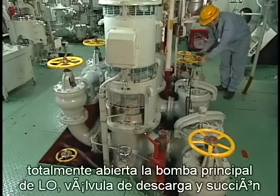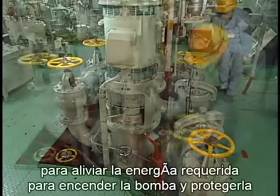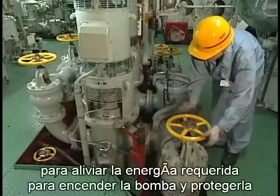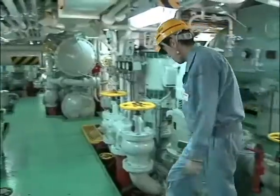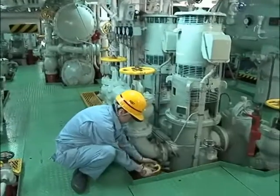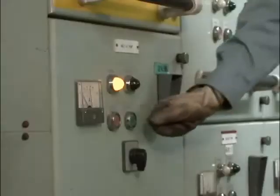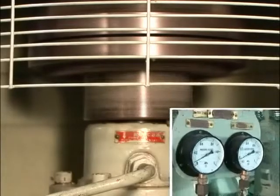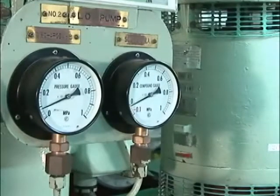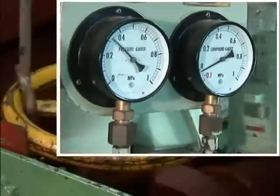Fully open main lubricating oil pump suction and discharge valves and the pressure regulating valve to alleviate the power required to start the pump and protect it. Then start the pump. Regulate discharge pressure after the pump has been started.